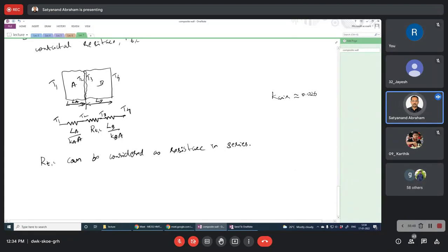If we put it into the gaps, instead of air, we are going to have the grease. Okay? Or any soft material, material that can be deformed very easily, metals like lead or something. If we put soft materials or soft metals into the gaps, obviously there also the conductivity is going to be higher than that of the air.